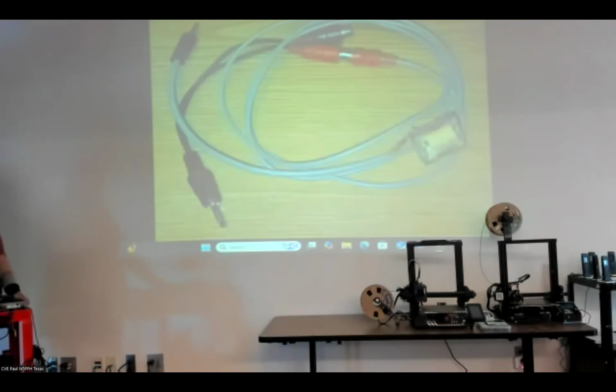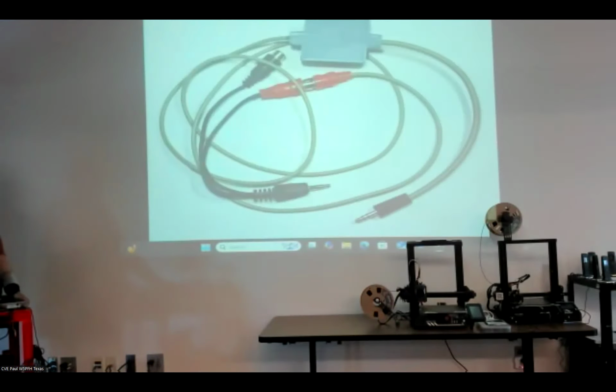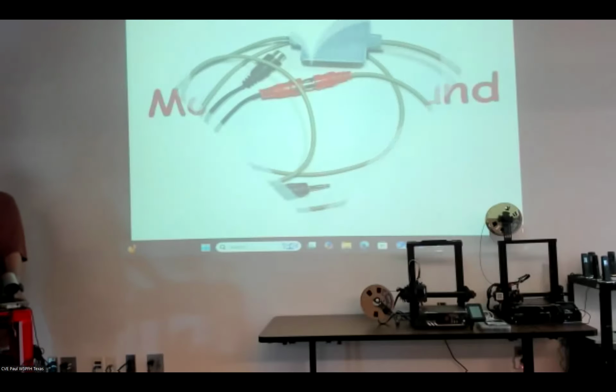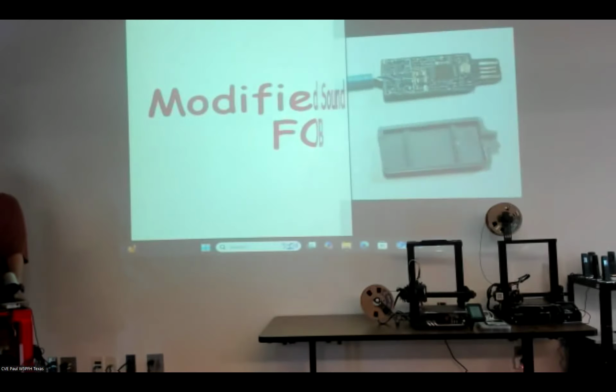Correct. You can do some gluing with PETG, but it depends on what kind of glue you're using and if it's solvent based or not. Right. So those are other things you gotta take into account. PETG will do really good for some outdoor applications. It's just a booger to print, from my experience.